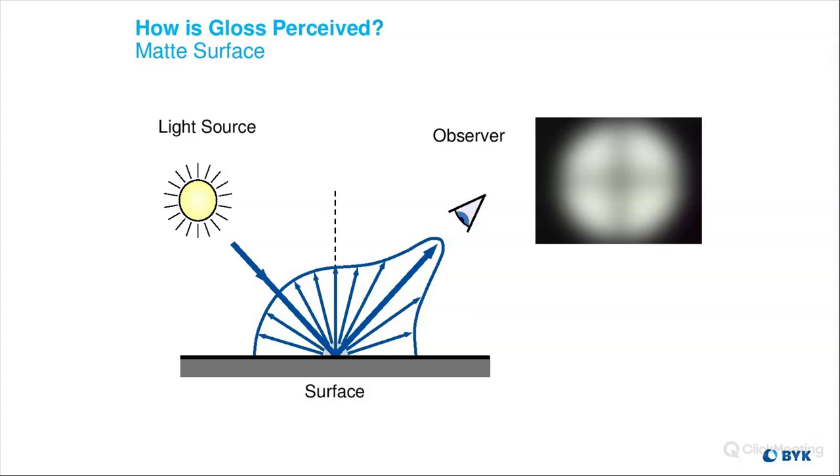Another one, how does film build affect gloss readings? Film build. It depends. It really depends on the material itself. For example, if we're talking about a clear coat and you have too much clear on a product, let's say your correct film thickness should be 3 mils, but you have 6 mils.